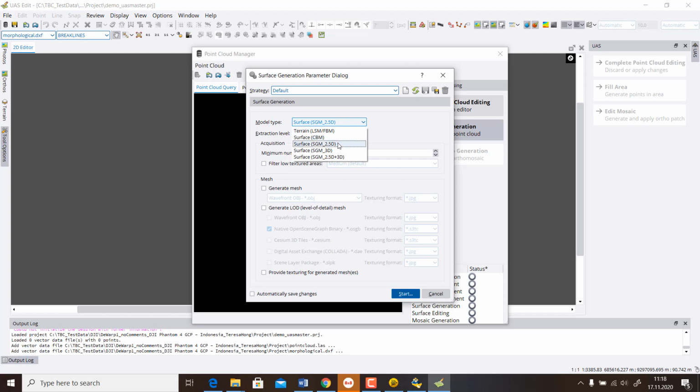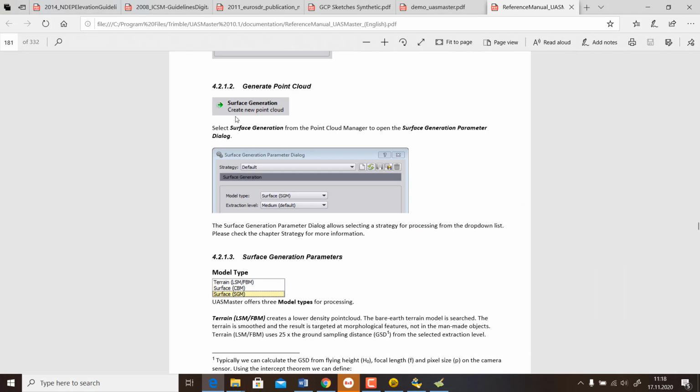And then if you have construction and buildings, then semi-global matching is the best choice. It takes the most time in production, but it is also the most detailed, and it enhances the building rooftops in a very nice way. Therefore it's a very good tool also for True-Orthophoto generation, which we can take a look at later on. The resolution that you define through it is explained in the manual, so I'll just skip to this part here.